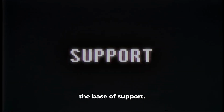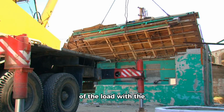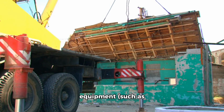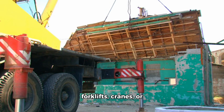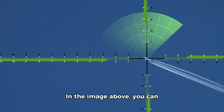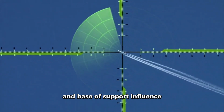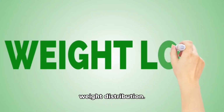Base of support. The area beneath a load that provides support is called the base of support. A wider base increases stability, reducing the risk of tipping. Alignment. Proper alignment of the load with the equipment such as forklifts, cranes, or trolleys aids in maintaining stability during transport. In the image above, you can see how the center of gravity and base of support influence a load's stability.